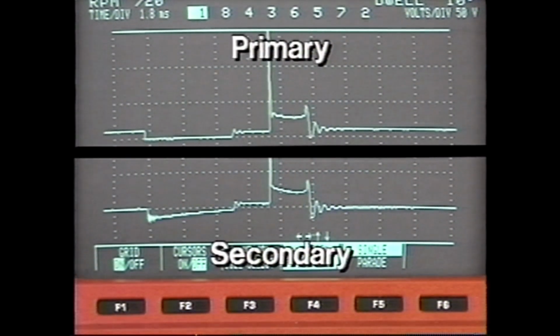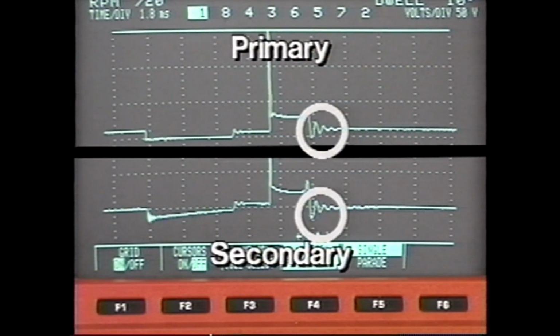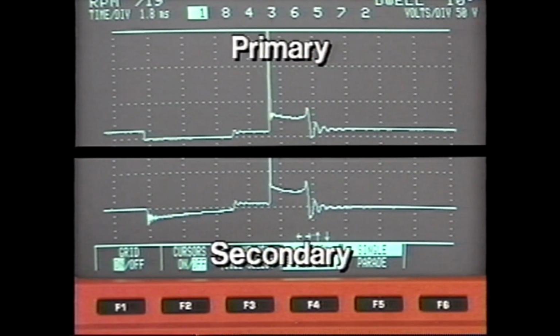When the spark dies, all remaining voltage is discharged as heat and the voltage decays. This is typically seen as 3 to 5 diminishing oscillations. Unused energy flows back and forth until no energy is flowing in either the primary or the secondary circuit. The cycle is ready to begin again with primary turn-on.